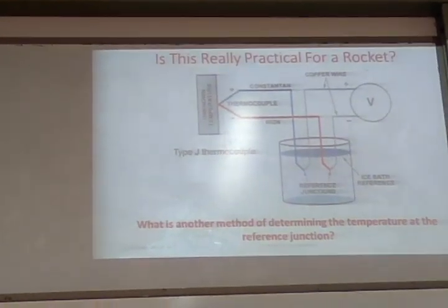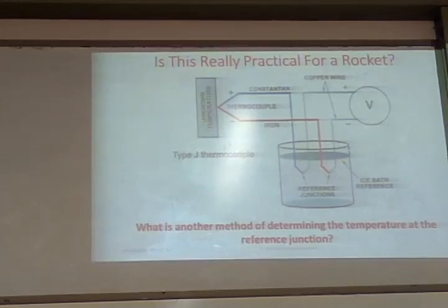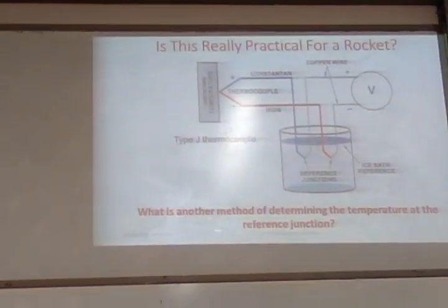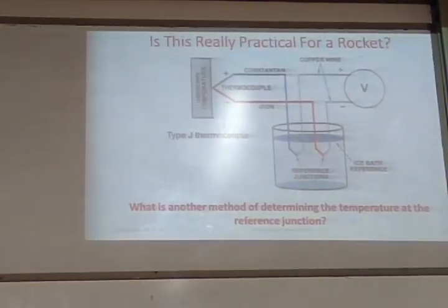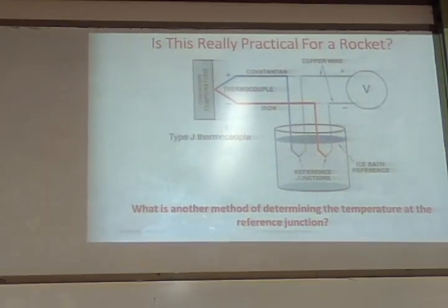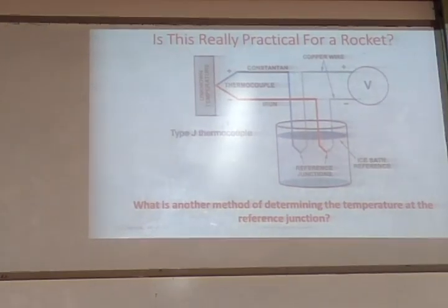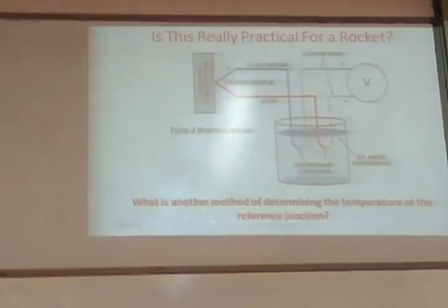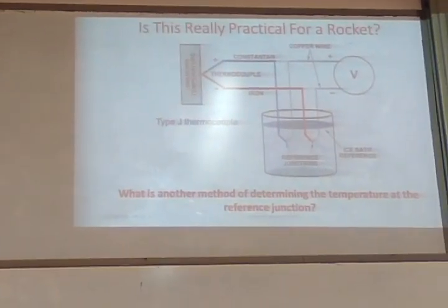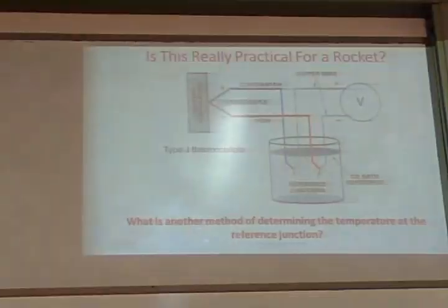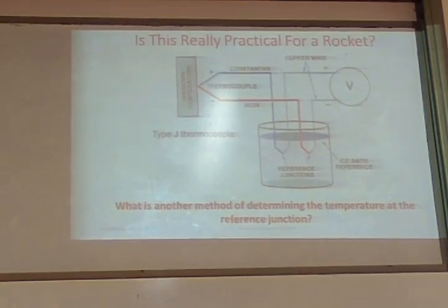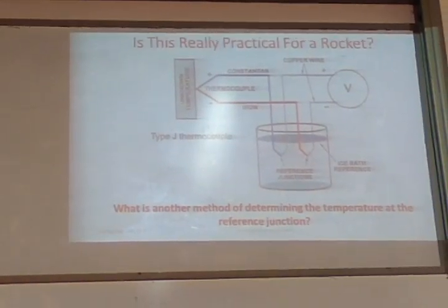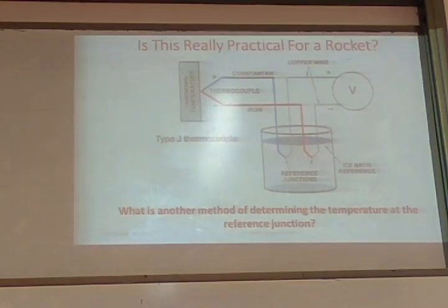The cold junction can be somewhere else. The hot junction can be at the temperature at which it is measured. The cold junction can be at room temperature, but we should know what the room temperature is, because from morning till night, the room temperature keeps varying. At least there can be 4 to 5 degrees of variation. So we should know what the temperature is.